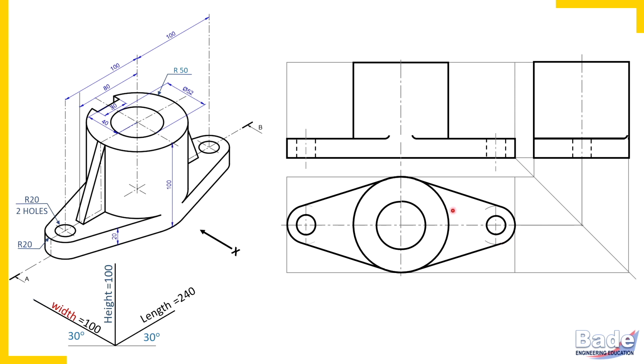Okay. Now from the back side also we must show that joint, but remember, on the back side there is a slot, so some extra work is required. Till then we'll not draw that joint here. So let's proceed with the hole here. This is how I projected the hole.